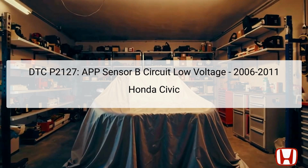For the Honda Civic models between 2006 and 2011, the APP Sensor B is typically located on the accelerator pedal assembly within the vehicle's footwell. Proper function of this sensor is vital for safe vehicle operation, as it directly affects the power and responsiveness of the vehicle. A reported low-voltage condition in this circuit may lead to performance issues or even impede the vehicle's ability to accelerate correctly. The knowledge of this code is imperative for effective diagnostics and repairs, as it provides a clear direction for troubleshooting.